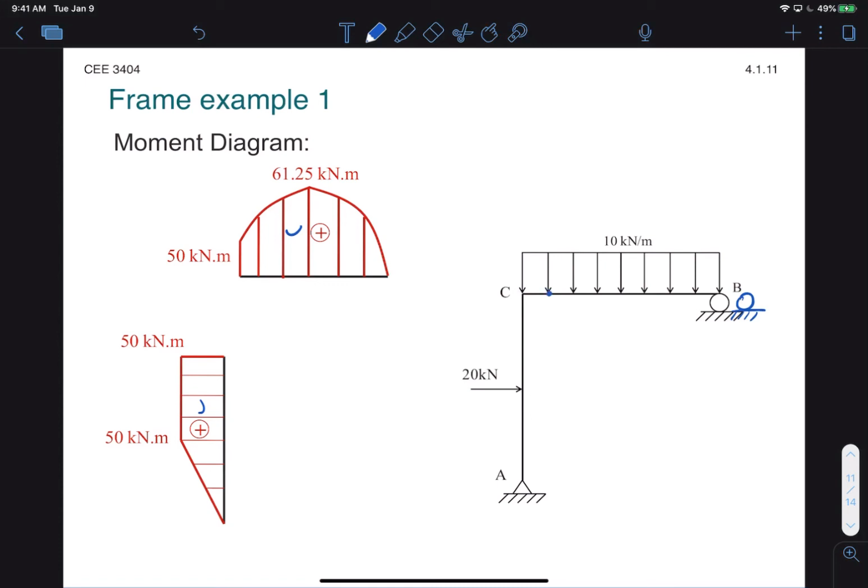Okay, so now I have basically my joints drawn out so I can start connecting them using the appropriate curvature. The load on the top beam CB is essentially downward. We have constant positive curvature for the whole beam, so it's fairly easy to draw like so. Next, I just have to join points A and C, keeping in mind the positive curvature here. And I also have to be conscious that the angle at C must be right.